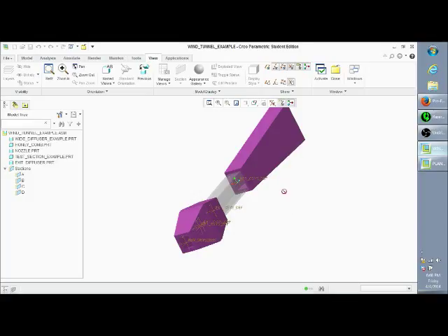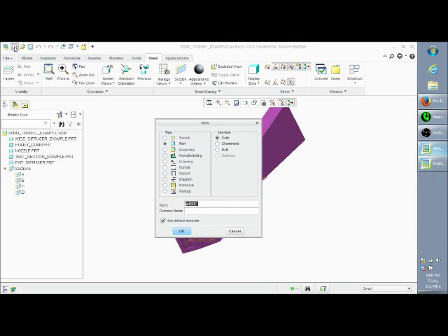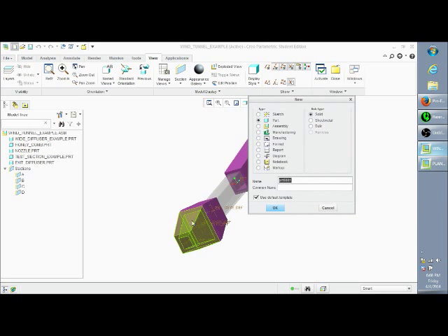And I'll show you what I mean by that. So let's create a new part. Go to New up here in the corner, or if you're in the main window that first showed up, it'll be a little icon over here to the side. In this window, make sure that Part is selected, and we're going to use the Solid type. For the name, you can call it anything. I'm going to create this first shape right here, which is our wide angle diffuser.